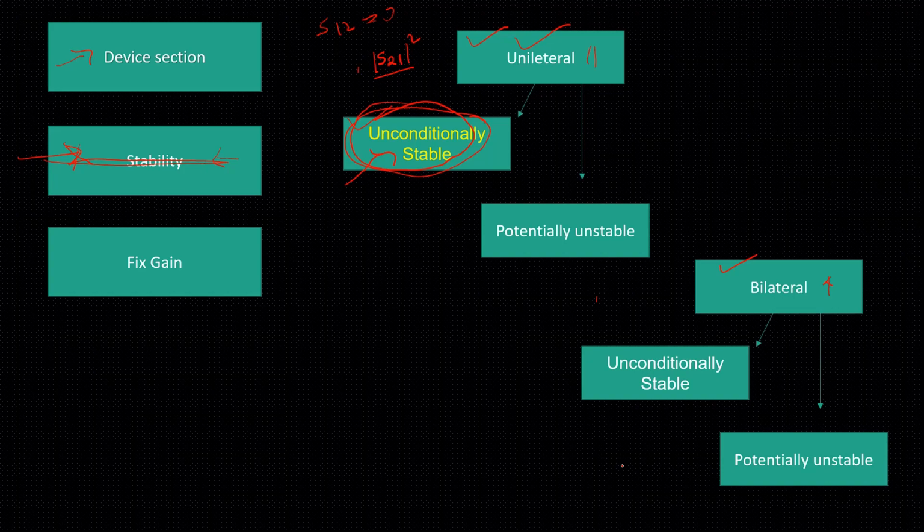So you need to fix the gain. And how do we fix the gain? We fix the gain by deciding on our gamma S and gamma in. As we know, in the equation of gain we have the factors gamma S and gamma in, so we need to decide on gamma S and gamma in.